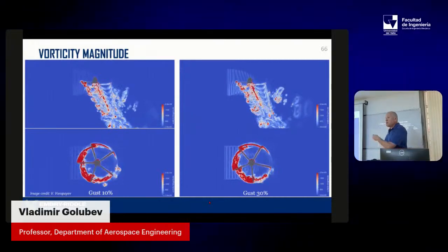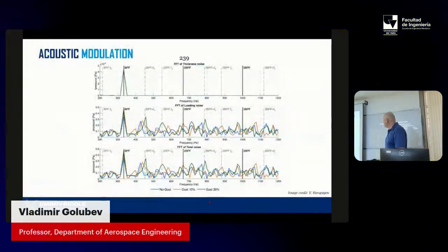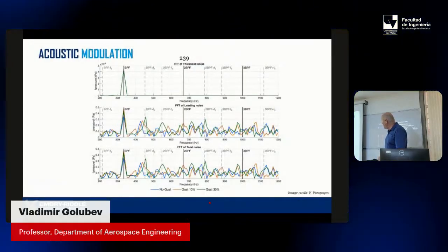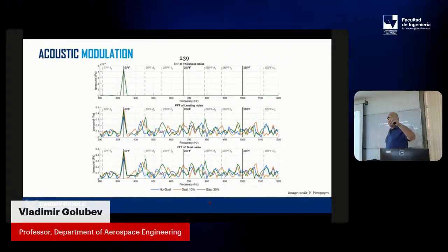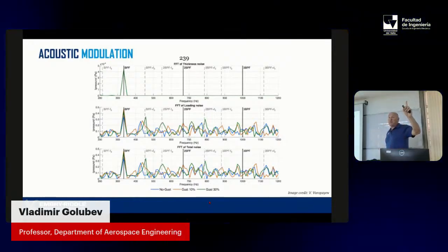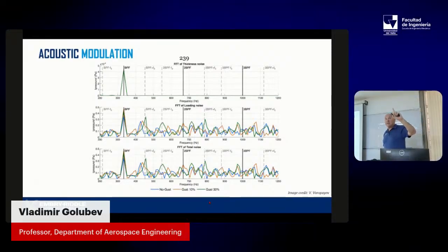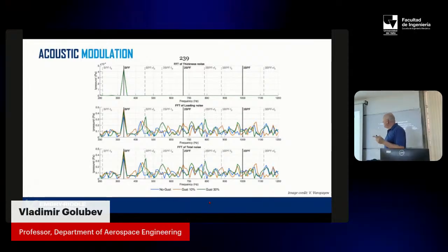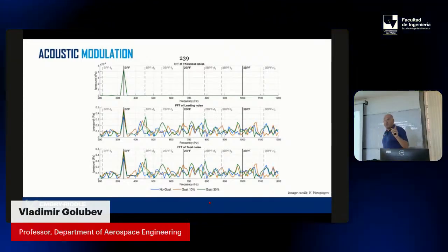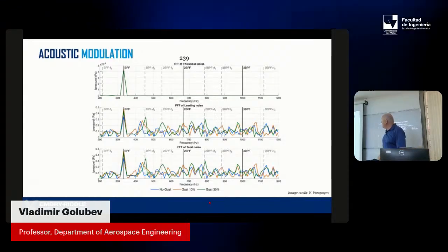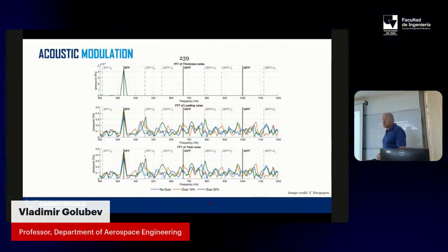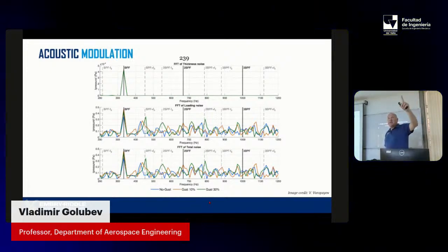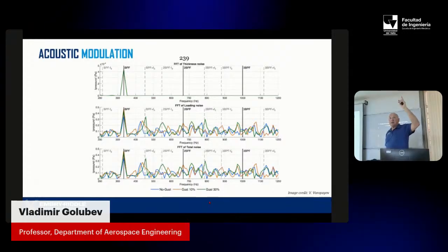Just to make sure, because this will be explained again in a separate presentation: we primarily found that the BPF is affected slightly more in the RMS value of the BPF thrust. Thrust is affected, torque is affected slightly as well at the BPF, but nothing at the gust frequency. What primarily gets affected is the modulation torque. It's BPF plus minus gust, 2 BPF plus minus gust, 3 BPF. These sidebands all of a sudden go up.